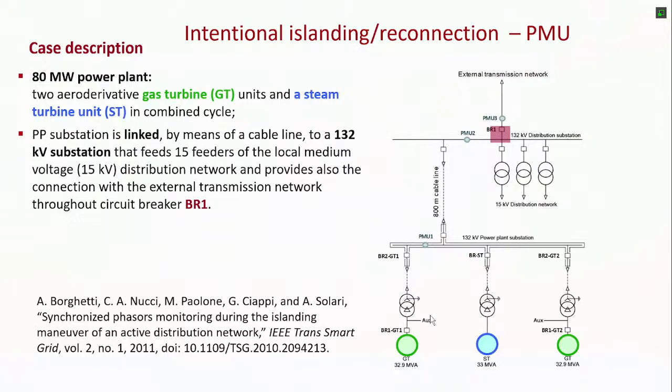And the others follow. The idea is to install these PMUs, and we have installed these 3 PMUs, two at the terminals of the circuit breaker, one before and the other after the circuit breaker. So we can also understand from the phasor measurement units when the circuit breaker is open. And the other one at the terminals of this line, in order to see what happens directly in the bus bars of the power station.